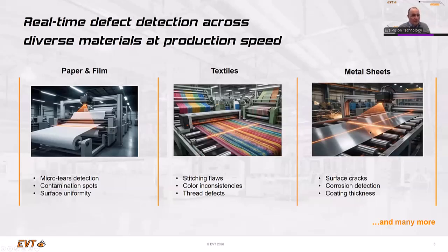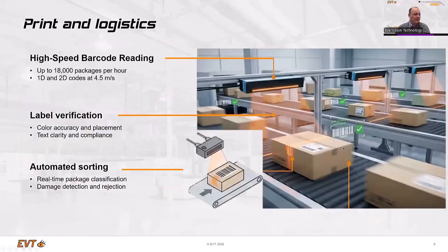But if you have this 1D camera, you only look at exactly this small area where the line scan is, and you can do the illumination perfectly, and then you get the defects very easily and very precisely.